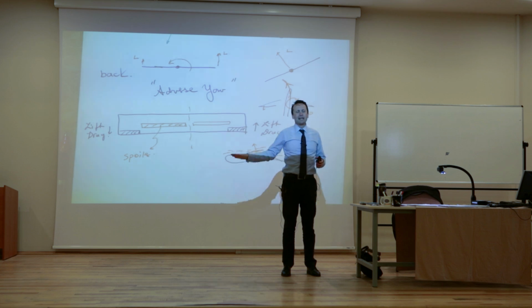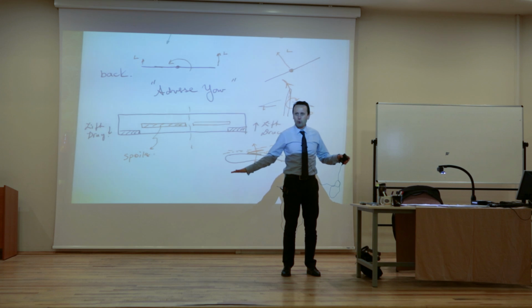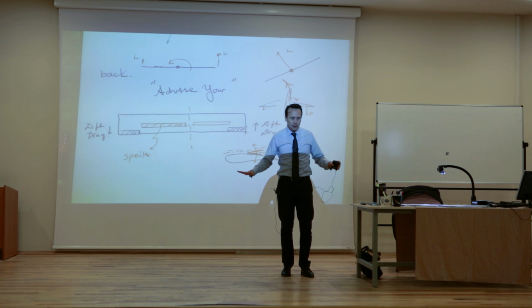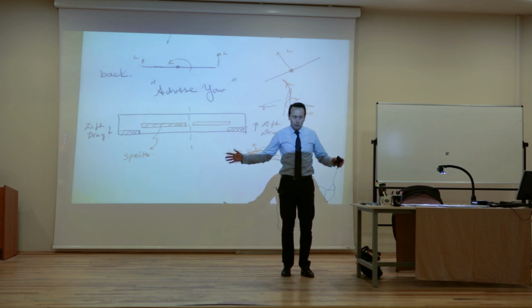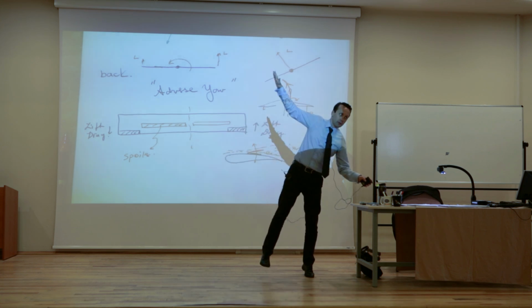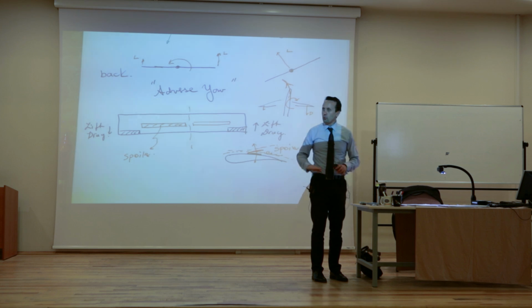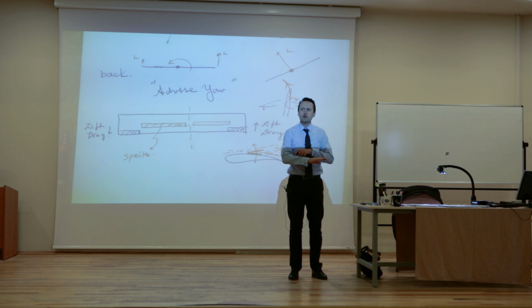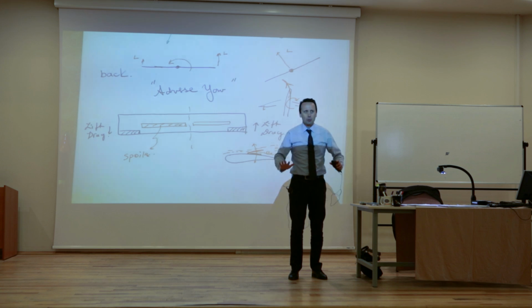Imagine that one wing is a little faster than the other one. That would be really horrible, because then you would have more lift in one direction and less lift over here when you land. For whatever reason, if you have more lift in one direction, you might immediately be doing this with the airplane. You don't want that. When your feet are on the ground, you really want no more lift, lots of drag. The best way is to open up your spoilers and really slow down, with no more lift.